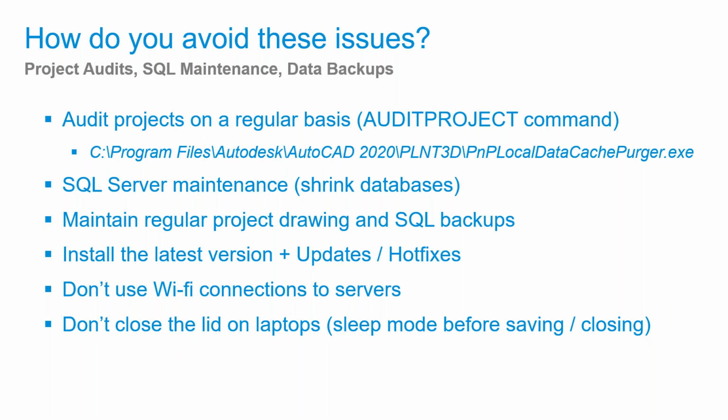Of course, maintaining regular backups of the drawing files in SQL Server, nightly if you can, is always good, so you have those to fall back on. And then as mentioned before, latest versions, latest updates, hot fixes, if you can stay on the latest version, if there's any kind of data integrity fix, that's going to be in usually the latest version. So if you get the latest version, you're going to have that available.